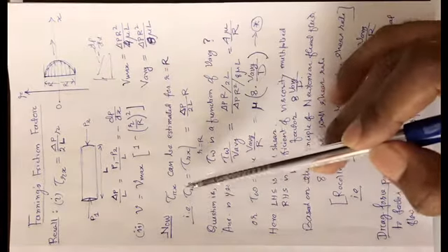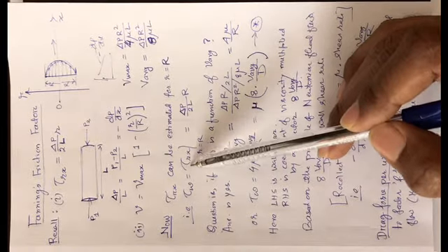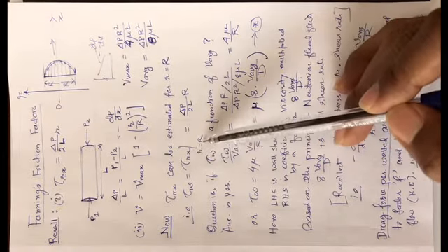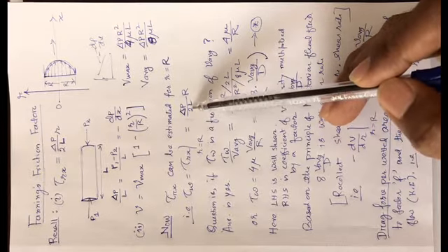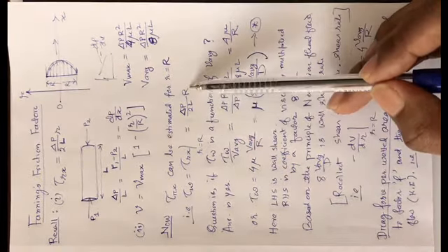So now we are going to estimate the term called wall shear. Wall shear is the value of tau rx when r is equal to capital R. So this is delta P by 2L into capital R. In this expression only r is replaced.